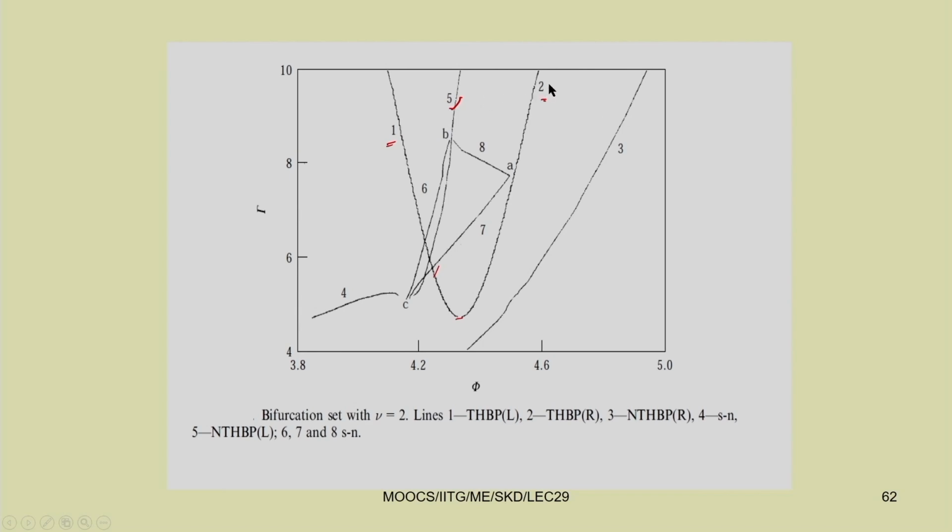So, you can have a set of periodic responses. Some of them will have their root in the trivial state and some of them will have their root in the non-trivial state. Due to the presence of all these periodic responses, there may be a chance that the period doubling route to chaos, or some other different type of route to chaos, can also be observed in the system.